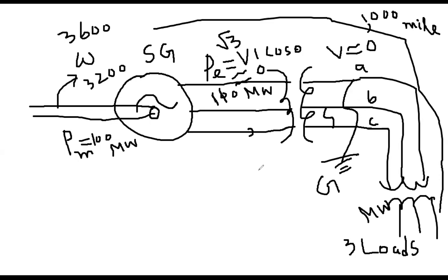So accordingly, there are different types of fault. It is called 3LG fault. 3LG fault means 3 is A phase, B phase, C phase, three phases. L means line and G means grounding. So it is called a three-line-to-ground fault. This example. Now the next example could be